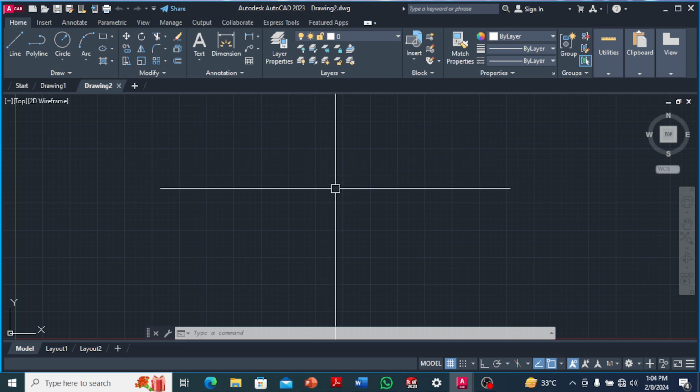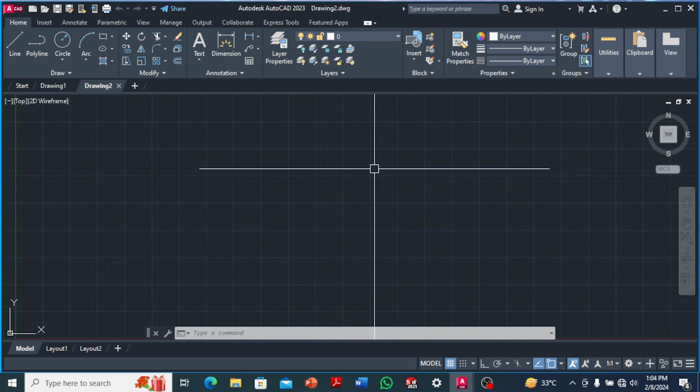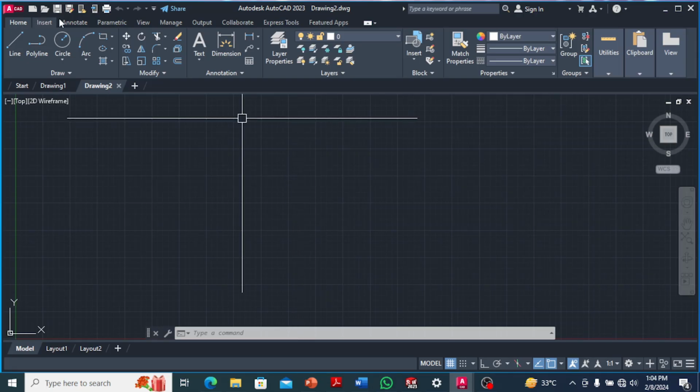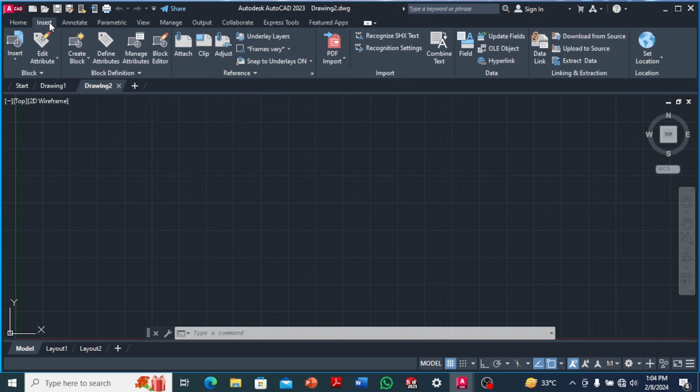Now the first thing we want to do on our 2D is dimensioning, how to, I think PDF, yeah, sorry. We are doing PDF first, how to import PDF and how to convert your already drawn files to PDF. Now, the first thing you do is, on the upper button on the user interface you set up last time, remember we have this insert. So you click on your insert. Once you click on your insert, it brings you to this menu, and you can see you have your PDF here. Once you click on this down button, you have your DGN import, and your PDF import.